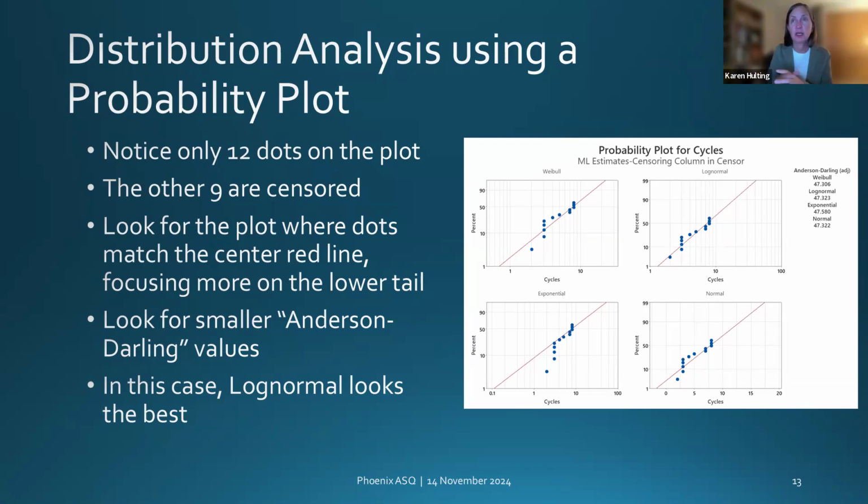They're failing too quickly. They kind of stack up, right? So it's really discrete kind of data that we are fitting down here. And so when you've got a whole bunch of failures at the 3rd cycle, those are going to stack up, and it's never going to fit that straight line just perfectly.